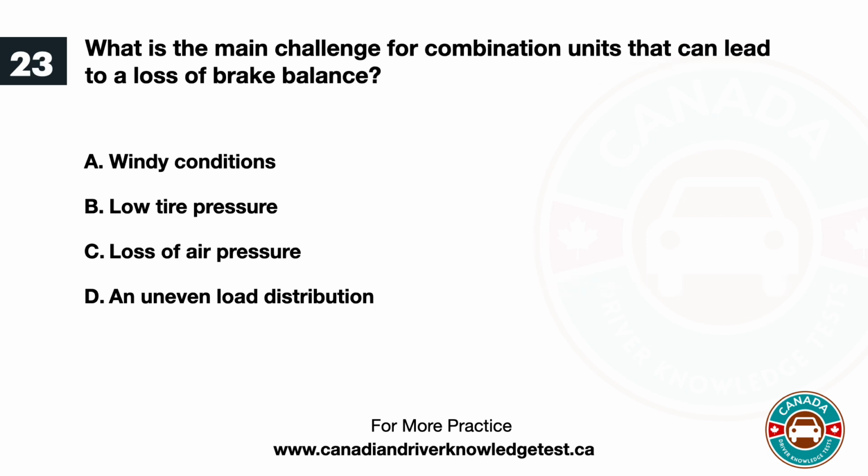Question 23. What is the main challenge for combination units that can lead to a loss of brake balance? A. Windy conditions. B. Low tire pressure. C. Loss of air pressure. D. An uneven load distribution. The answer is D. An uneven load distribution.